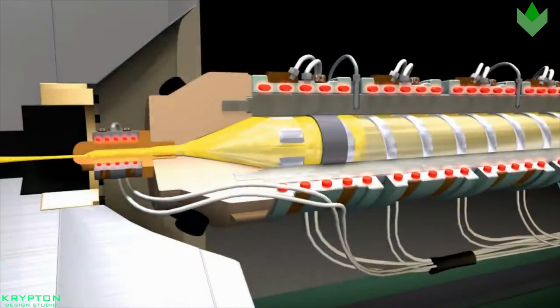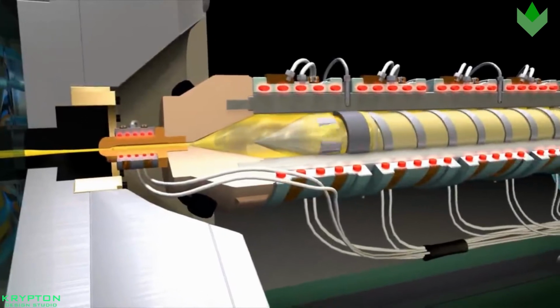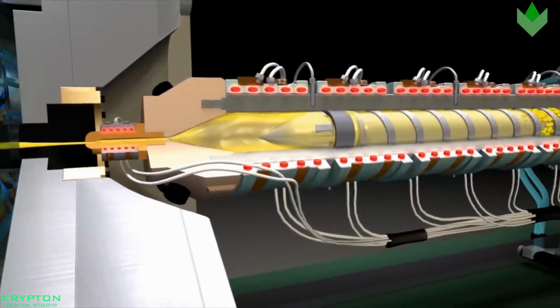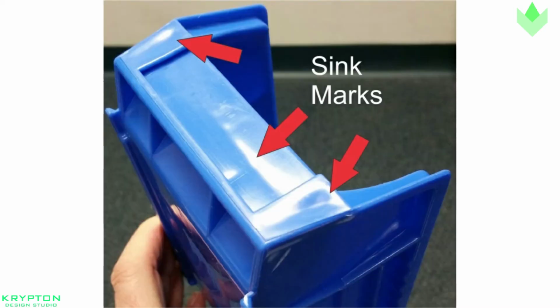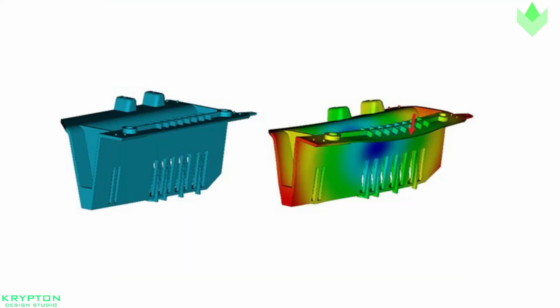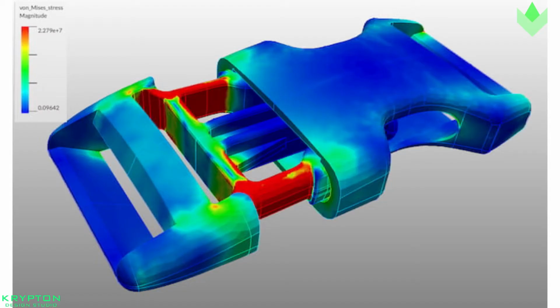As the material cools and the molecular bonds reform, setting the resin into the rigid form, these stresses are in effect locked into the part. Part stresses can cause warpage, sink marks, cracking, premature failure, and other problems. While some stresses in injection molded parts are to be expected, you should design your parts with as much consideration for stress reduction as possible. Some ways to do this are adding smooth transitions between features and using rounds and fillets in possible high stress areas.